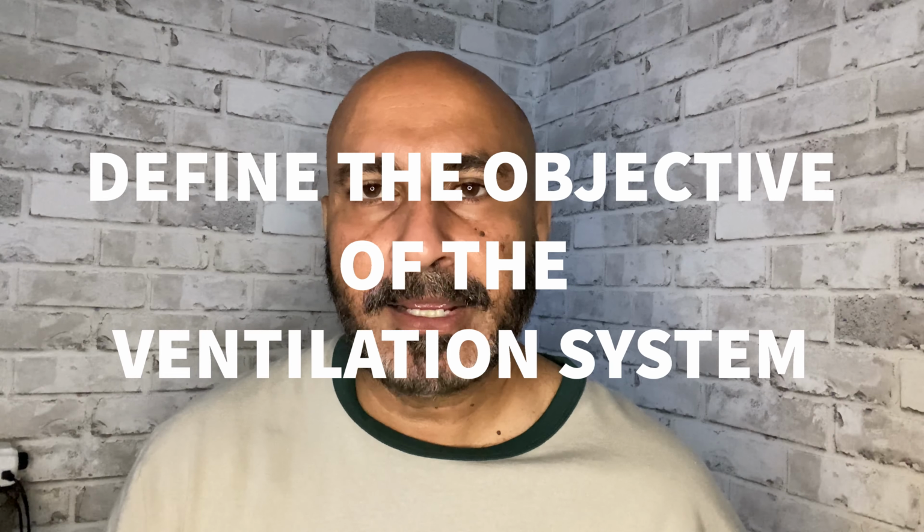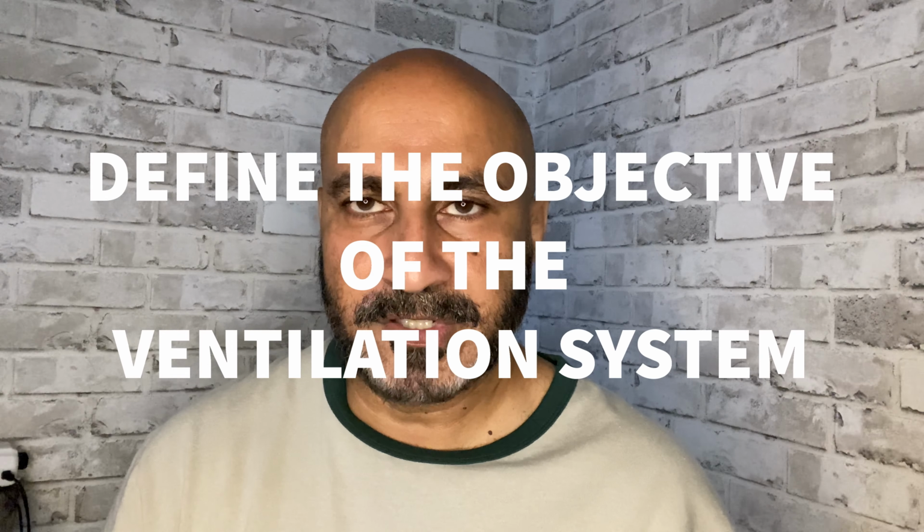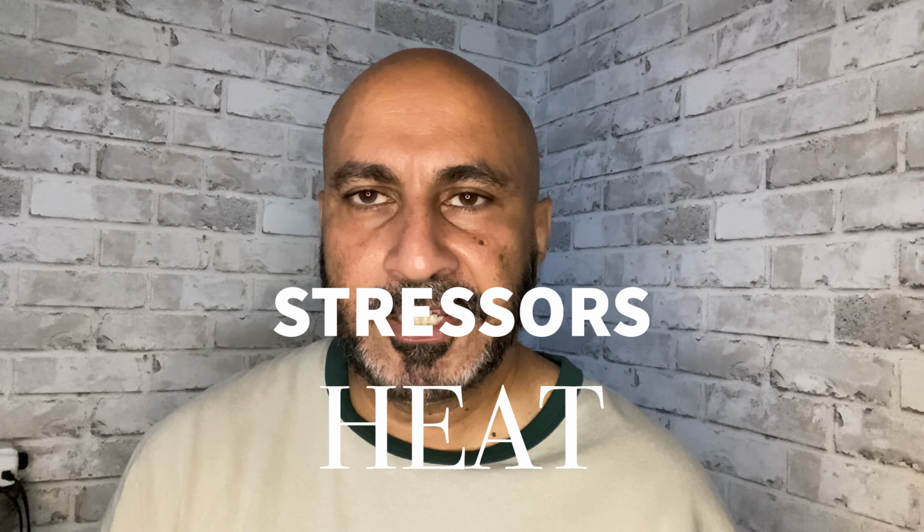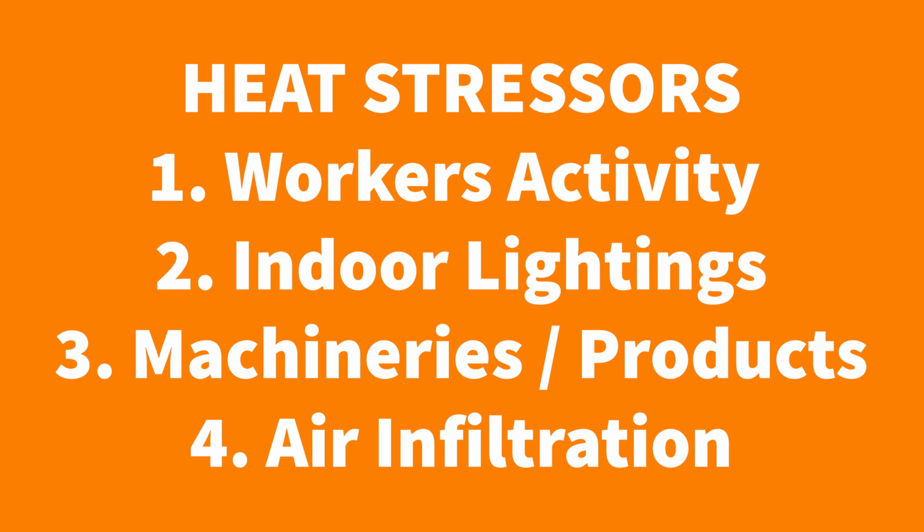Next, let's identify why we are doing this ventilation in the very first place. Are you having any heat releasing elements, internal loads? All right, heating elements, are you having plug points? Are you having equipment which is going to generate heat? Are you going to have people working? Are these people working light? What kind of activities are they doing? Are they light work or heavy work? Because depending on the type of activity, the heat release from your body varies. Your body will release higher heat when you're exercising or doing work which requires higher intensity of actions.